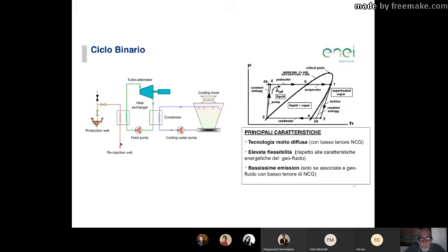But then, after you pass your fluid into your first heat exchanger, you have a two-phase fluid, made of non-condensable gases saturated with water and a liquid phase that is saturated in non-condensable gases.